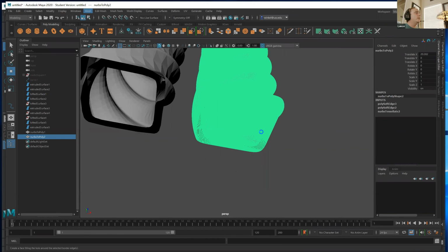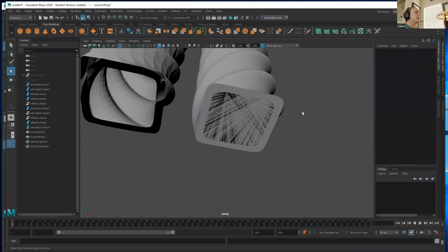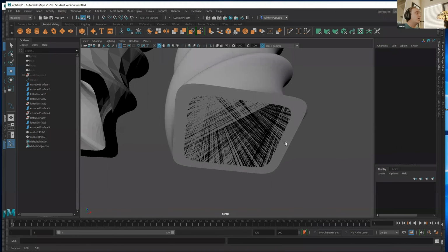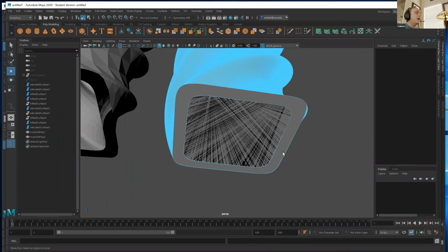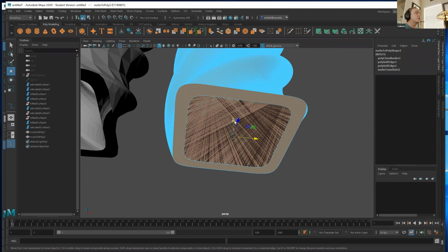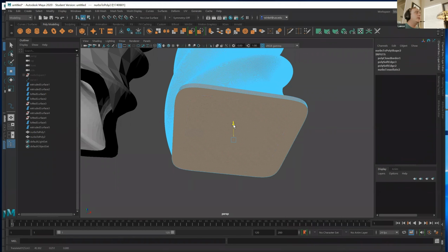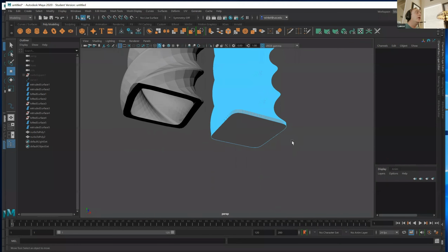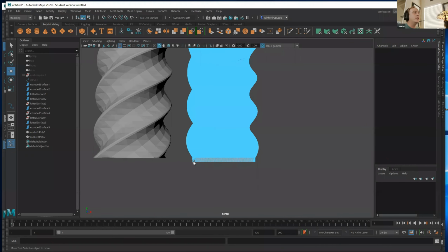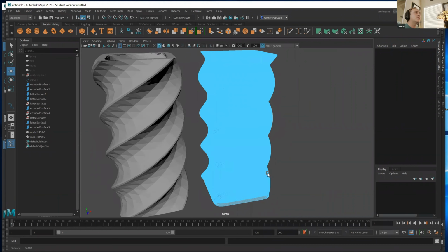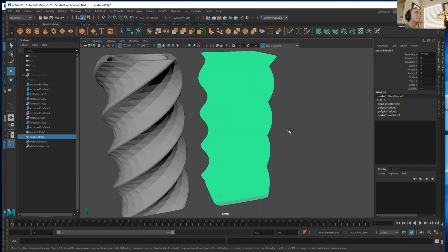When I fill the hole on the bottom, it's going to leave a gap that I should have had like a 1 or 2 millimeters of thickness. It's going to take a little time for it. So see how I've got that little artifact right there? Now, it's going to be easy for me to fix because I'm just going to grab this face and pull it down, but it means the bottom of my model has kind of a little bit of an artifact I'm not happy with. But now that I brought that down by a few millimeters, it's got thickness. So it's now actually like a drinking glass, okay?